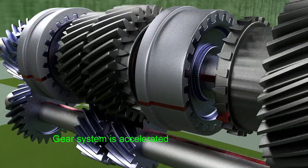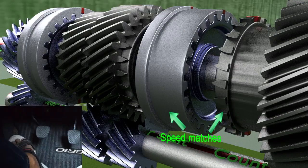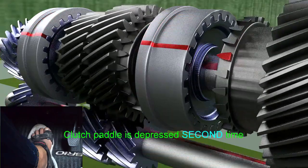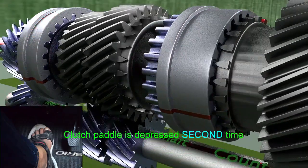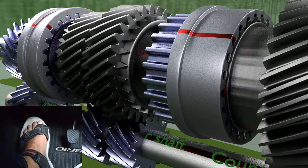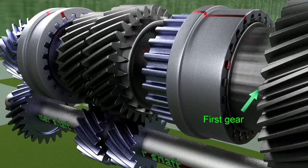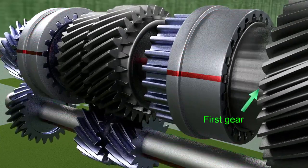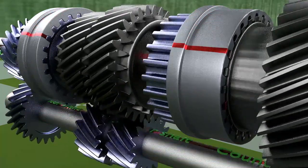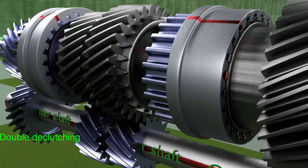When the driver thinks that the speed of the first gear matches the speed of the shift sleeve, the clutch is disengaged again, a second time, and the first gear is engaged. Then the clutch is re-engaged by releasing the clutch pedal. Thus, now power is transmitted through the first gear. Thus, in order to change the gear, the driver has to disengage the clutch twice. Therefore, it is referred to as double declutching.